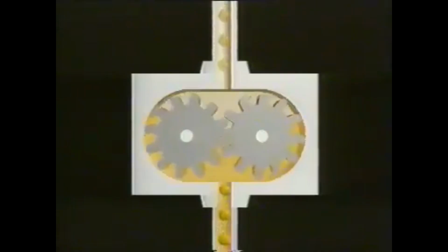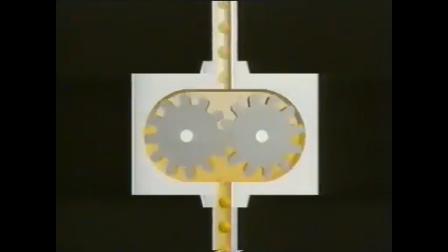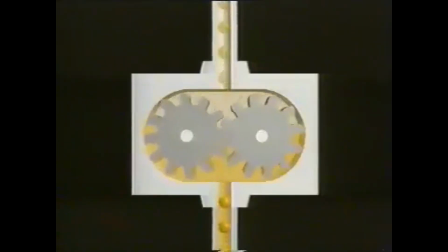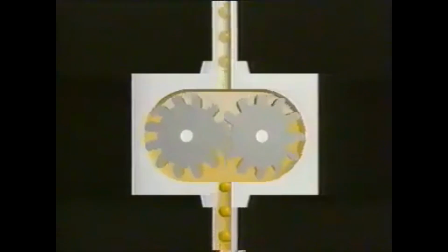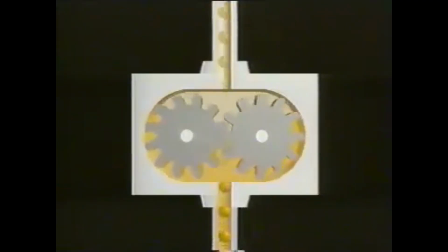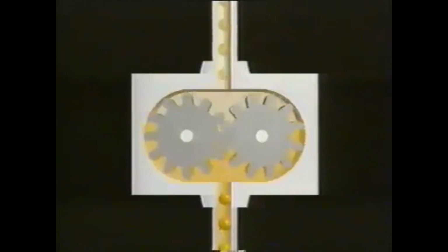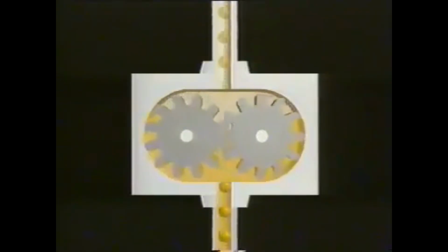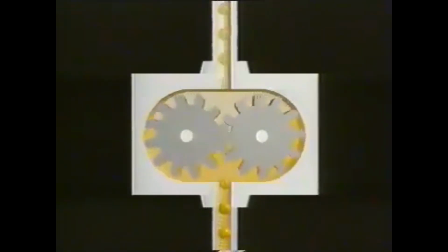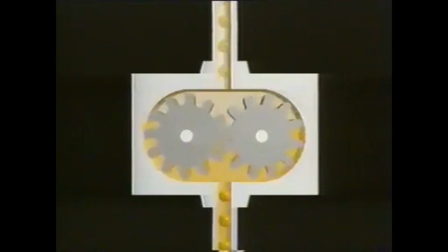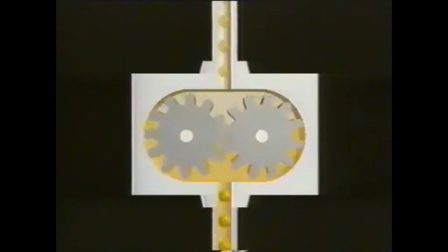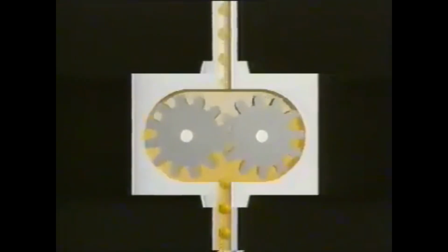The hydraulic oil, which is under pressure, drives two intermeshing gear wheels. It flows along the chamber wall and becomes almost unpressurized because it only has to overcome line resistance as far as the oil reservoir. An important characteristic of hydraulic motors is the consumed volume V. This is the quantity of oil that the motor can take in one revolution. Rotational speed N is calculated from flow rate divided by consumed volume. Any calculations of hydraulic systems must always make allowances for leakage oil loss.